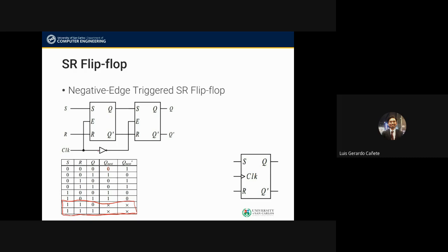It's really because of the fact that your inputs here on the second stage would transition from being 0, 0, which is already an unknown state. We can't transition from 0, 0 to 1, 1 at exactly the same time. But there will be cases where this one will go to 1 first, right? So we would then have 0, 0, 1, 0, and then 1, 1, in which case this will become 1.